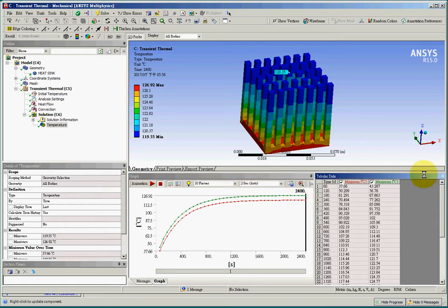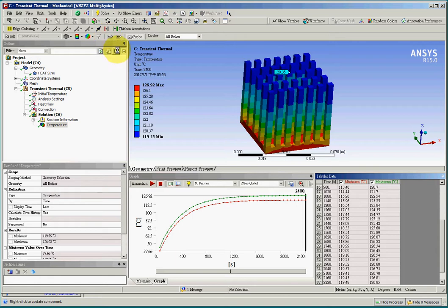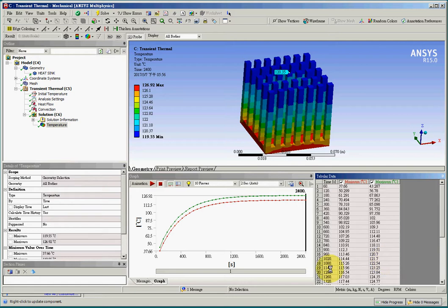So I can probe this number, and this is the result that I probe, right? I'll display the result of this probe spot. Okay. Now, this is the temperature that I have tapped, and beware that in the steady state thermal analysis, the final temperature is also 120 degrees C.